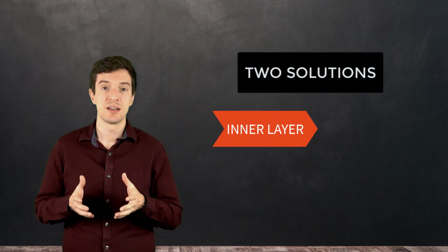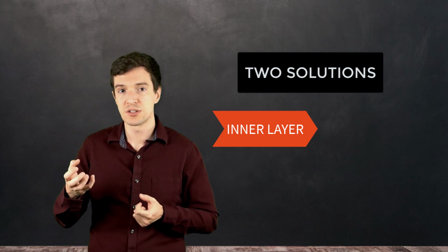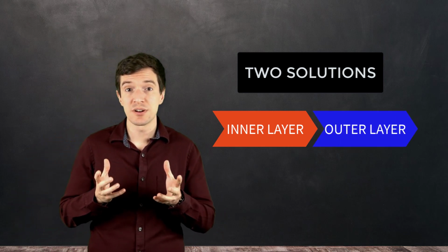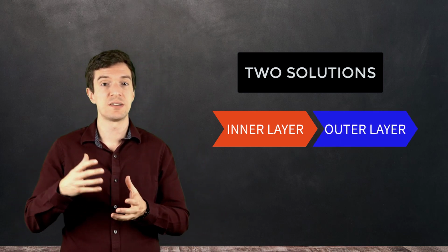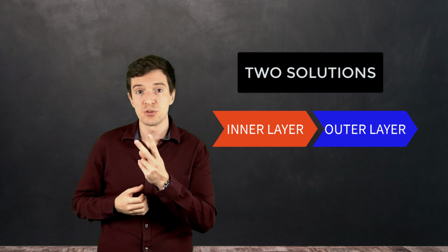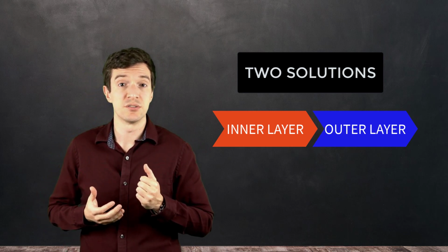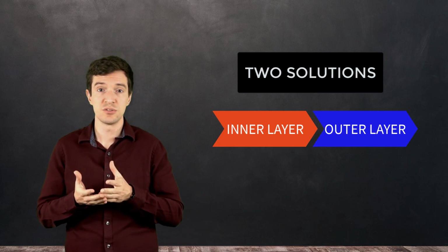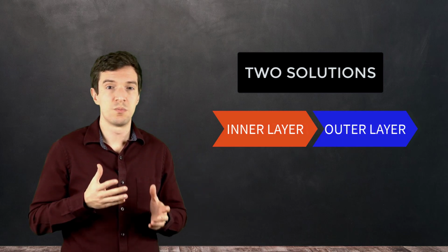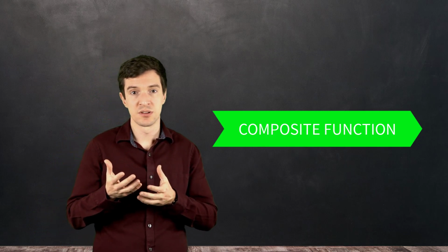The equation can provide us two different solutions for two distinct regions. One is the inner layer dominated by the viscous effects, where the no-slip condition must be satisfied. The second one is the outer layer, where we are approaching the free stream velocity and the viscous effects are limited. The two solutions are valid only in their respective regions. Van Dyke introduced the matching principle. The idea behind it is to blend the solutions of the two regions to create a composite function that represents the entire region.